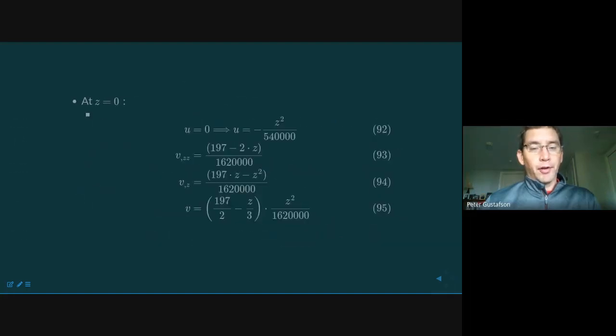I don't need to go through every last detail here, but we know the boundary condition: the displacement at the root is going to be equal to 0. We can calculate slope at the root as being equal to 0 because this is, again, a cantilever beam. We can calculate the second order derivatives.